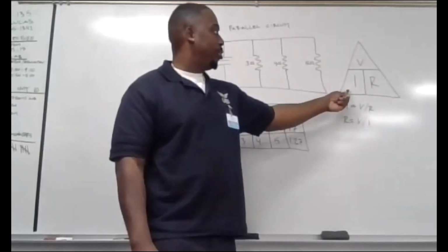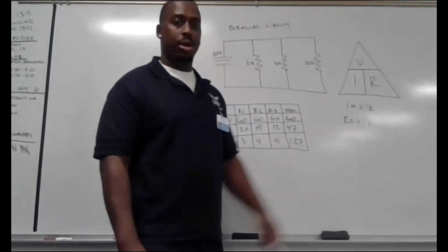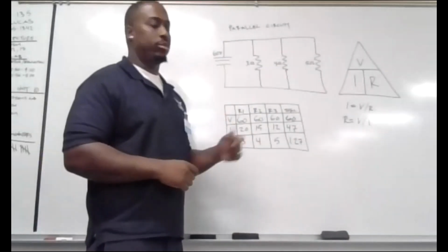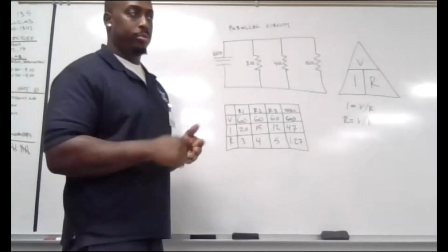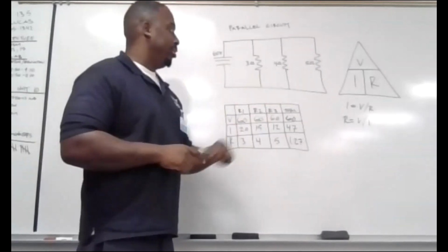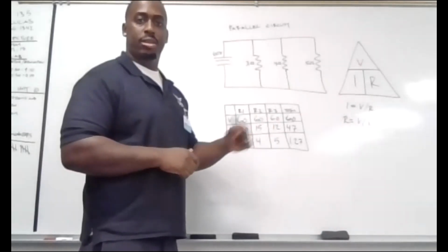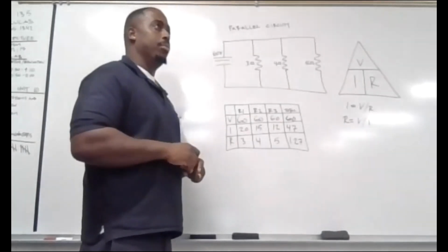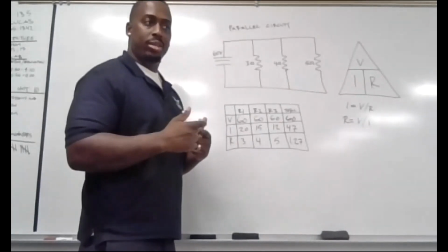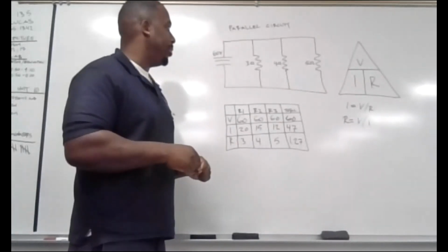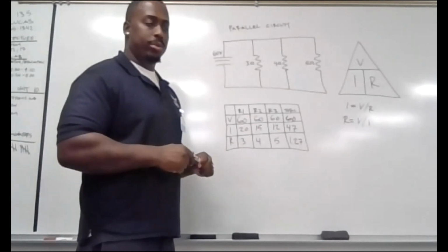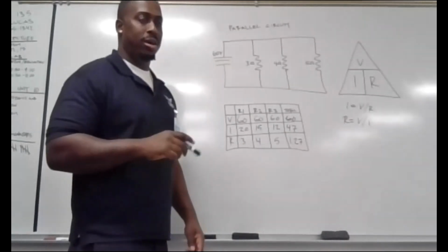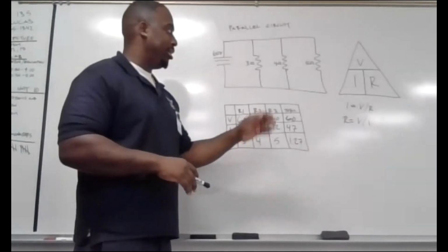So you see why it's so important to utilize this little diagram when it comes to these little mathematical equations regarding electricity, you know, ohms, volts, and resistance. You can lean on that. You don't have to worry about memorizing what does what. The more you do it, the more it'll stick. As we move forward with some of these assignments, it'll start to stick. But when in doubt, draw it out. V over I next to the R, and you can figure out any of these equations.